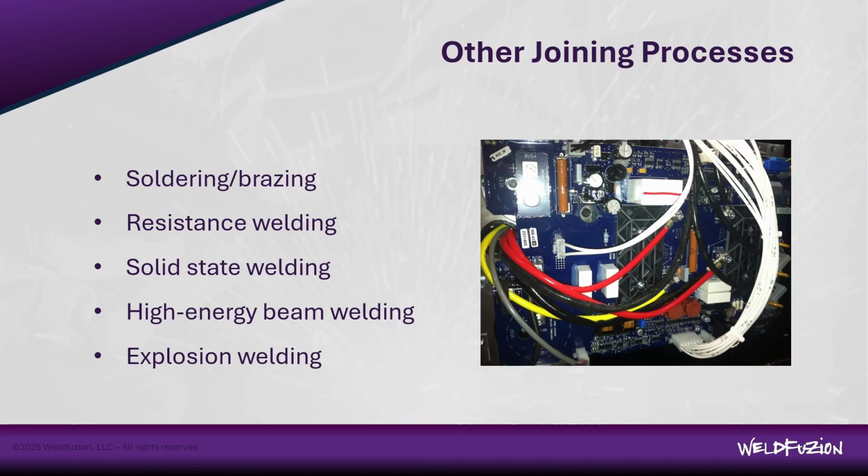And explosion welding is something that's pretty interesting. It's again like friction welding. You're using plastic deformation of charges set on the thin sheet to impinge it down on top of the thicker substrate. So quite a neat process. Typically done in mines, and that's something that you may see on the History Channel or Modern Marvels. I think I've seen an episode on it out there.